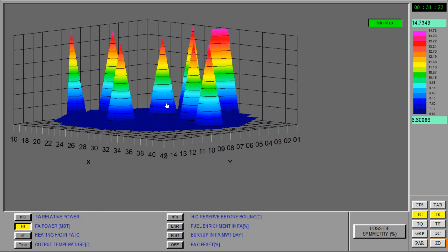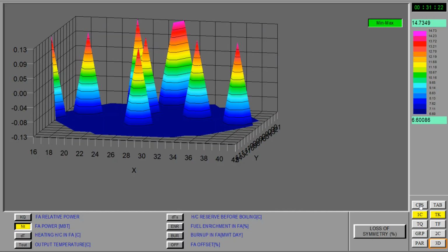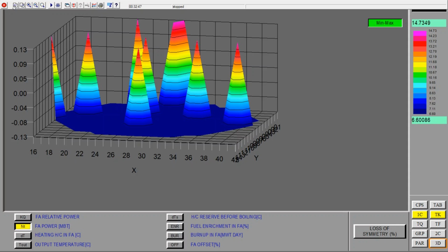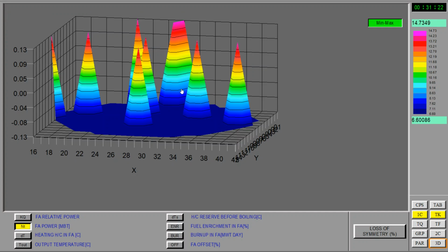We cannot analyze anymore these outputs now because the reactor is shut down, but according to what we saw during the decrease of power of the primary, I would say with some level of confidence that the boiling is not accounted for in the primary model, nor physically, so it's not accounted in the thermohydraulical exchange model, and nor in the neutronics model. So that's my initial hypothesis, and that's my conclusion. Not 100% sure, but I'm like 80% sure of this looking at the data outputs.